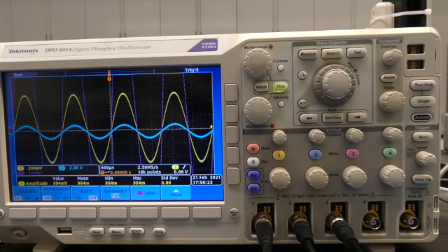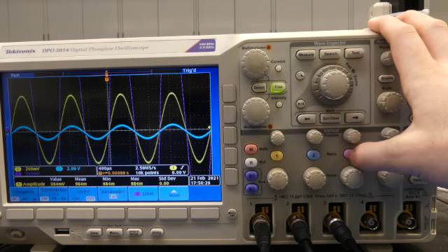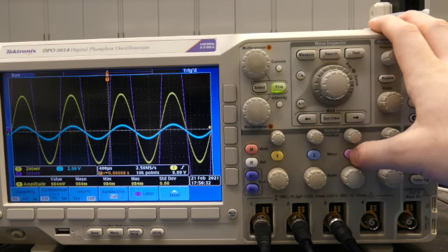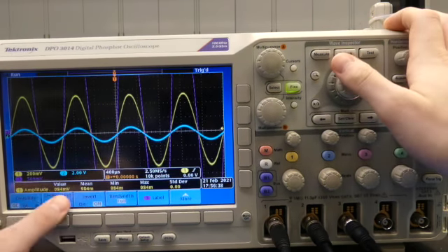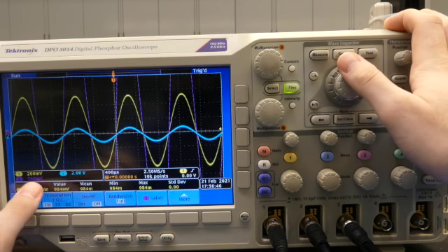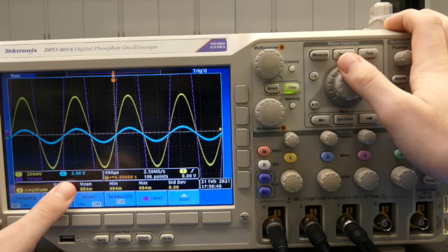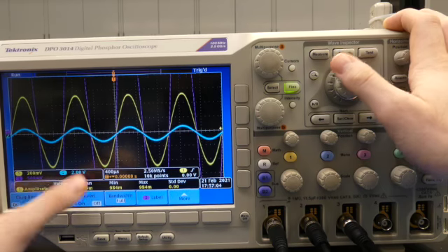Now, you'll notice that we can't really see all of the 3rd channel, and everything is kind of all over the place. I'll start by saying that these 3 values right here is the value at which it's hard to see the purple. I'll try to demonstrate with the 1st and 2nd channels the most. With the 1st channel and the 2nd channel here, you can see it's set to 200 millivolts and 2 volts. Let's see, make sure I get this right. Yep, that is the Y scale setting of the oscilloscope.